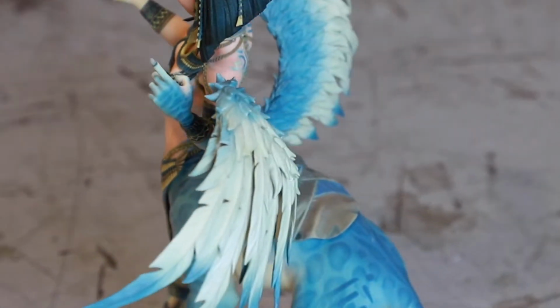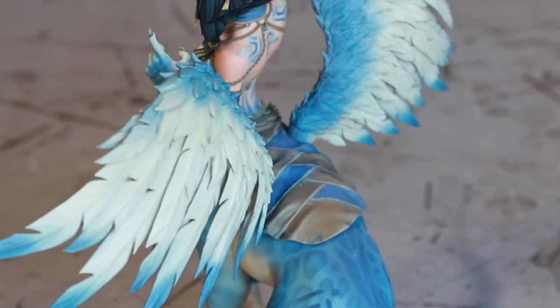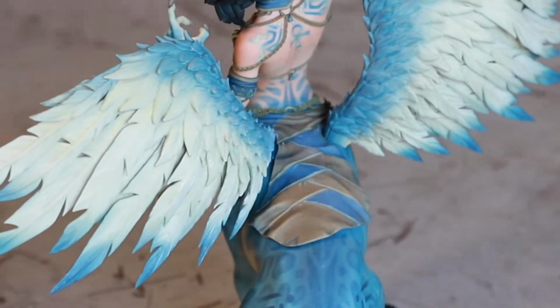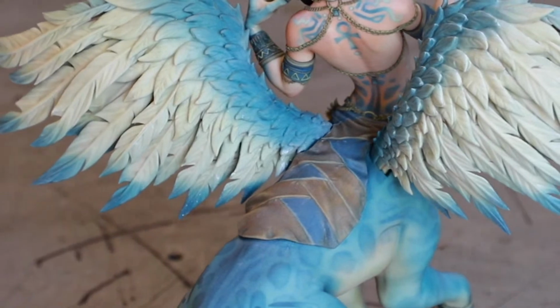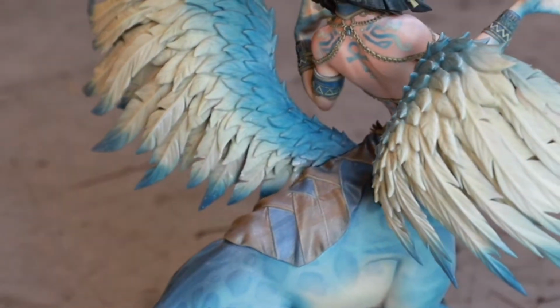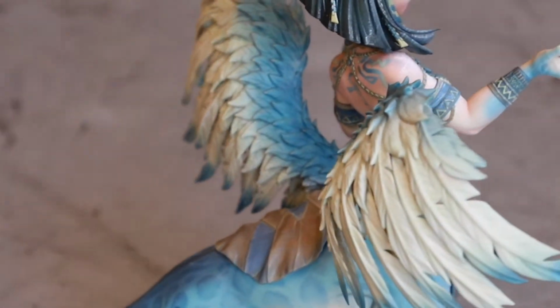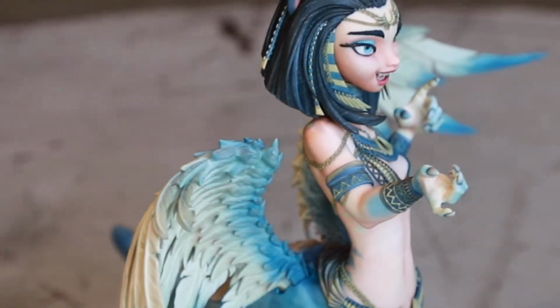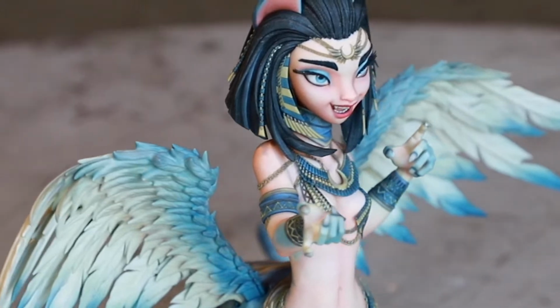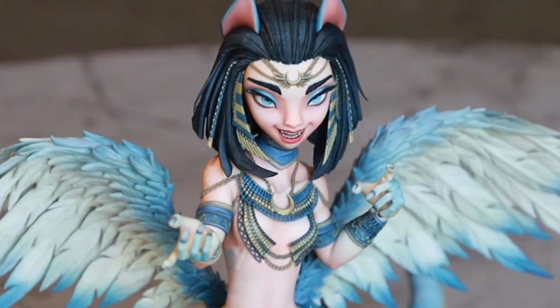Each of those wings is a separate piece, so that we were able to print this laying down flat and to maximize the print area of the bed. Having a 20 inch by 20 inch by 12 inch print area allows us to do larger pieces, but sometimes like this you may want to separate those pieces in order to optimize faster build time.